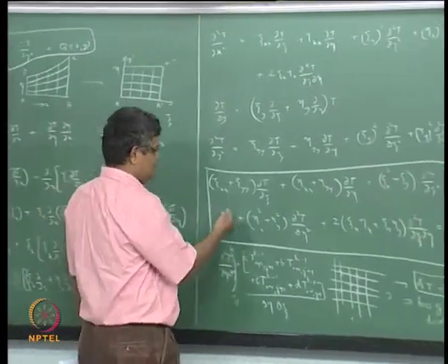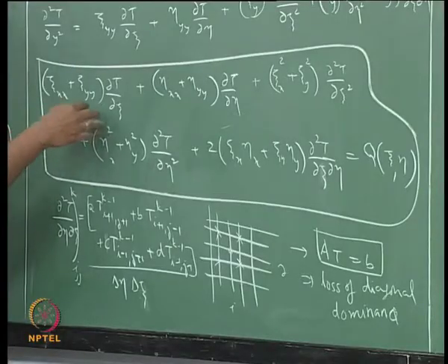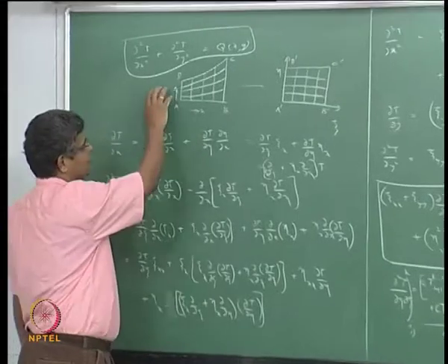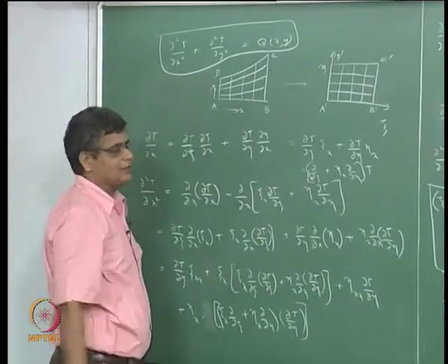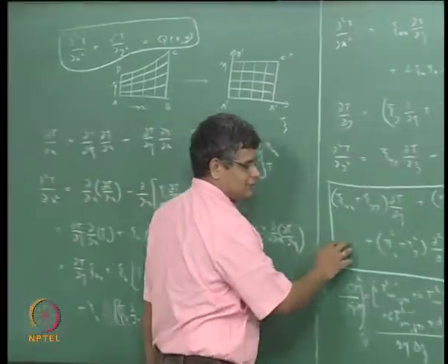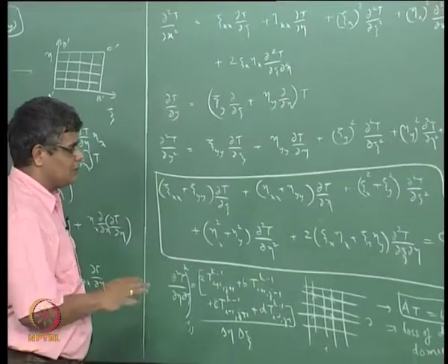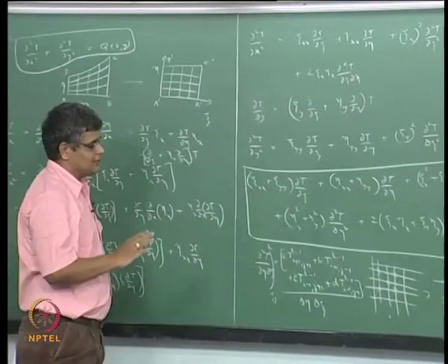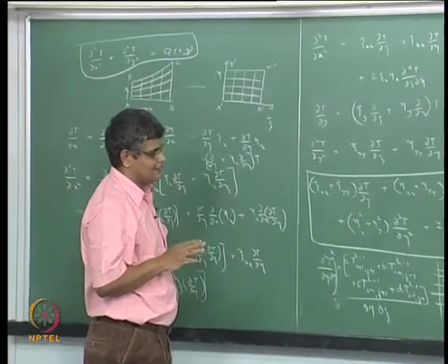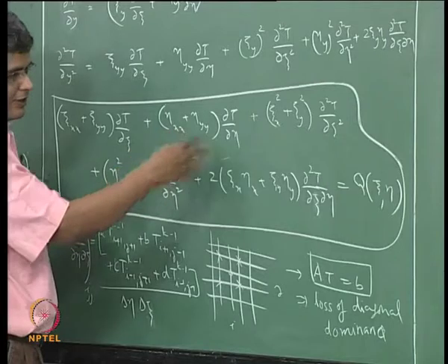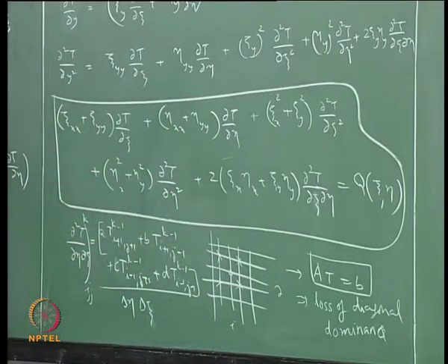So, this is an artificial thing that is being introduced into the equations because of the transformation. Okay. One can show that because of the transformation, the mathematical nature of this equation does not change. That is, if we are starting with an originally elliptic equation like this, then even this transformed equation will also be elliptic. If you are starting with a parabolic, then this will be parabolic. Okay, so that condition is maintained, that assurance is there that we are still dealing with the parabolic or elliptic equation as we started out with.